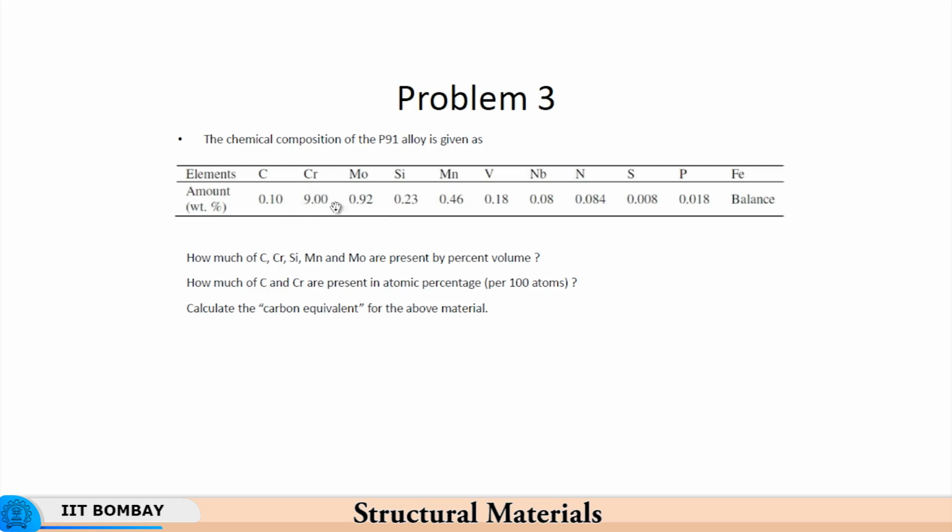Chromium for corrosion resistance is important, because you have water which is heated to a high temperature, and the pH of water might not exactly be 7 at all times. So, because of that this chemical composition has been obtained for boiler grade steel.